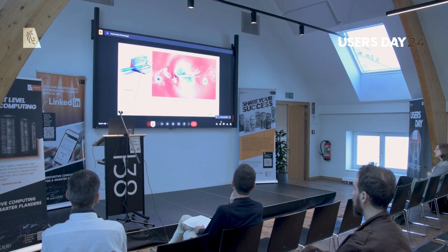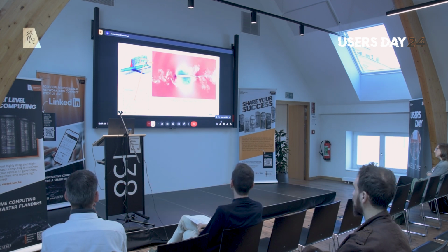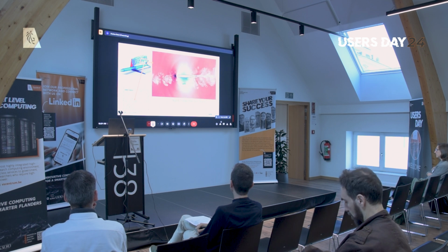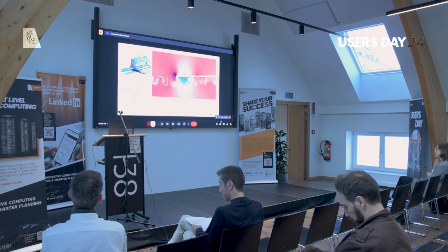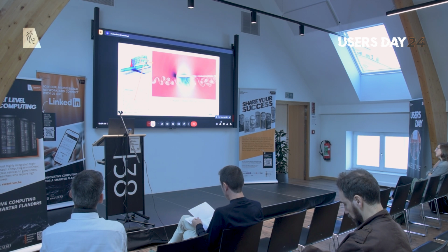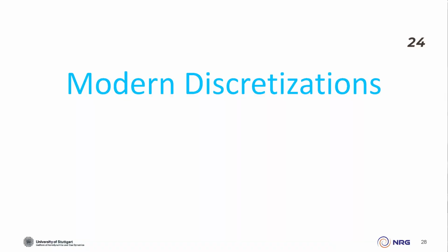and clearly an HPC type of problem that we need to solve. So by being able to do these large-scale computations, we are able to predict what type of flight situation might occur that is right at the boundary of this current flight envelope, and that currently prevents us from building more efficient airplanes. And by the way, this is a 1 billion degree of freedom computation, so 10 to the power of 9 per variable for this tiny piece here. And again, you can see why this is such a multi-scale problem. It would be completely infeasible to resolve a full aircraft with this level of resolution.